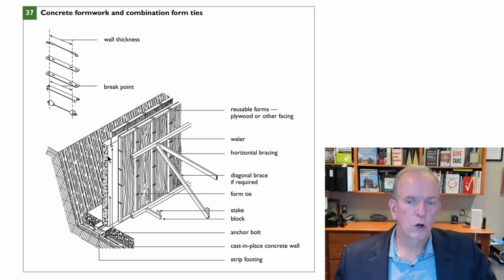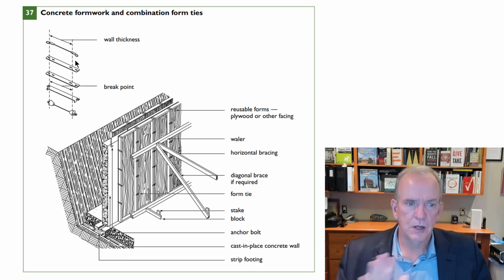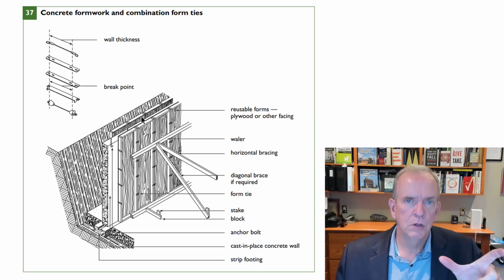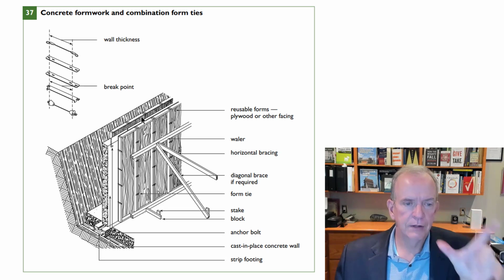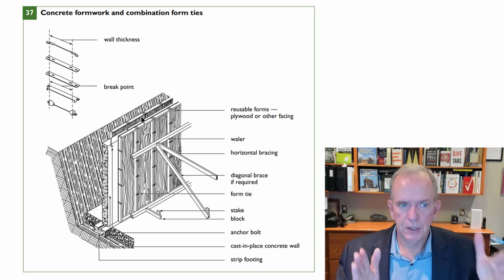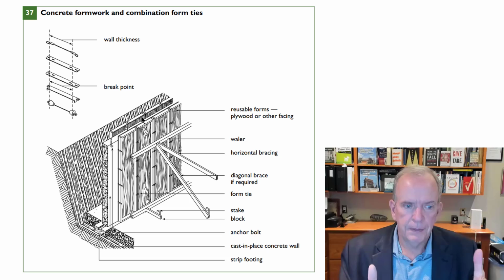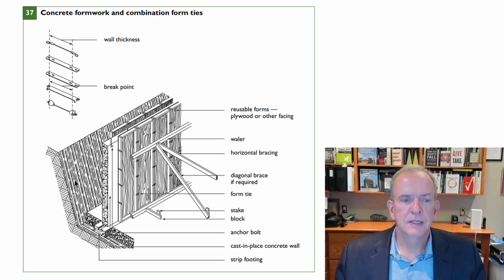And so you use formwork to actually build it. There's many different formwork companies out there, and they have standard forms, and they just drop into place, and you pull them out. You use snap ties, and these ties tie the forms together, and then they snap off. So they're left in the concrete, and then they're patched to stop it from leaking. But they hold the forms at the exact spacing, whatever you're using. So if it's a 200 millimeter wall, approximately an 8-inch wall, about 7 7/8, then that would be the snap tie distance that the forms would tighten up against, so that would hold it at a consistent thickness.